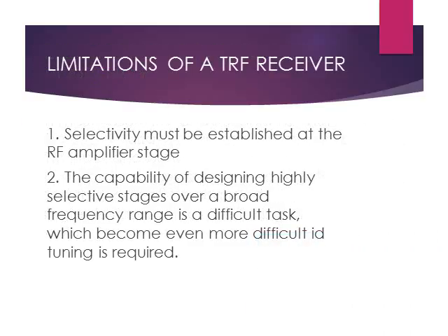But there are certain limitations of a TRF receiver. Selectivity must be established at the RF amplifier stage, which requires complex circuitry. The capability of designing highly selective stages over a broad frequency range is a difficult task, which becomes even more difficult if tuning is required.